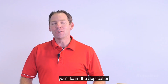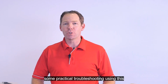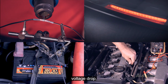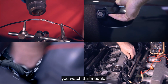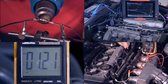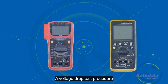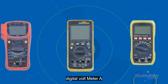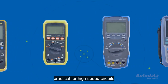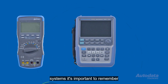In this module, you'll learn the application of voltage drop theory and some practical troubleshooting using this technique. If you're unfamiliar with voltage drop, we recommend that before you watch this module, you check out our other training videos in the series. For most automotive circuits, a voltage drop test procedure can be performed with a digital voltmeter. A digital storage oscilloscope is more practical for high-speed circuits like ignition, injector, and communication systems.